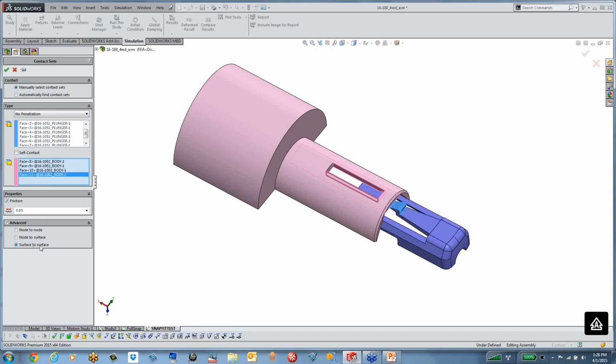So if I use surface to surface, you can see that there are a lot of permutations and combinations, and a lot of constraint equations that we are solving behind the scenes. Each face, let's say face number 1 on the first selection box, can actually interact with faces 8, 9, 10, and 11 on the second selection box, and likewise. So a lot of constraint equations get created because we are using surface to surface contact, and that can actually take a lot of time.